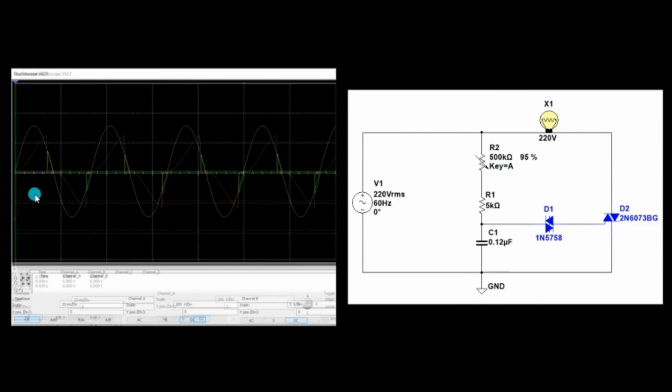And then this is the voltage waveform. You will notice here this white, it is not very visible, class, but this is actually white. The white is our 220 volts AC input. That is what you see on the oscilloscope, that is for the input. And then this orange, this is the charging of our capacitor, the voltage across our capacitor.